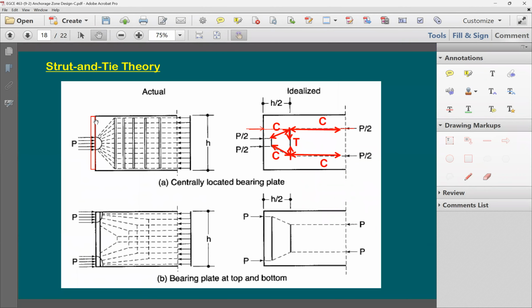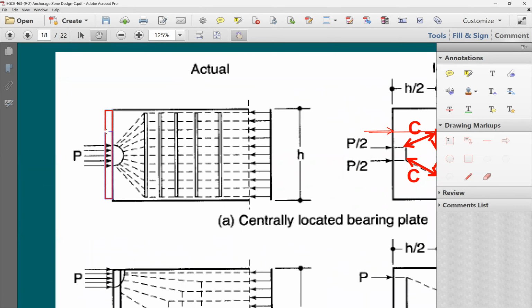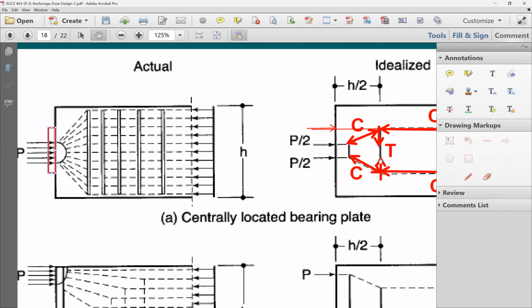Therefore, if I put here a big steel plate to have the same depth, the same cross-section area of the beam, you're going to end up with no tension force. If I start to reduce this plate size, I'm going to be creating more tension stresses and more tension force right at this location. If I put it to be extremely small, what happens to the tension force developed there? This is going to show that this tension force is going to get larger and larger.